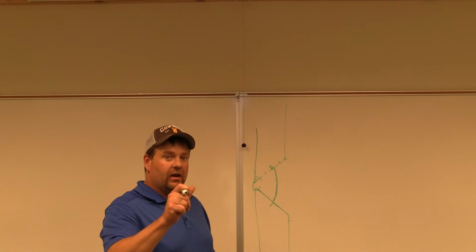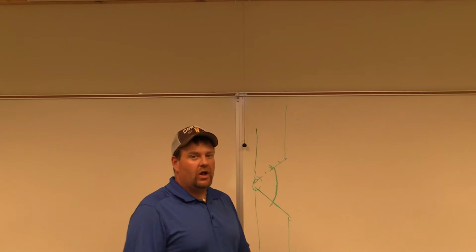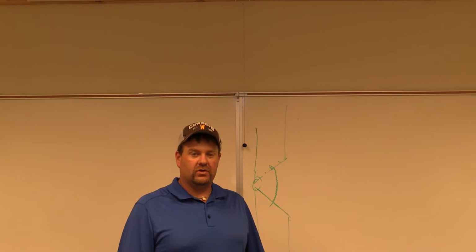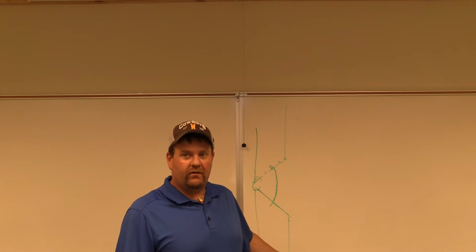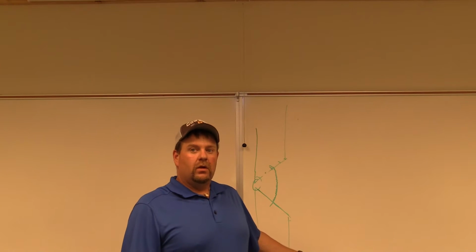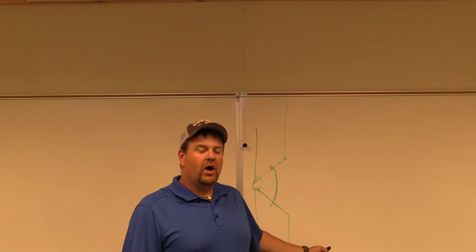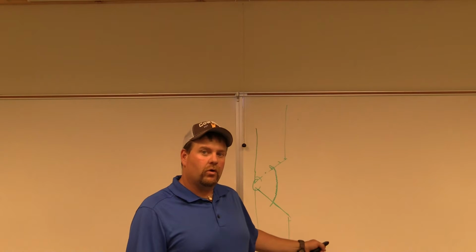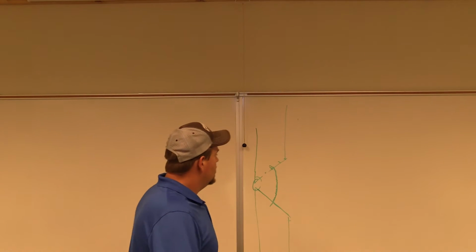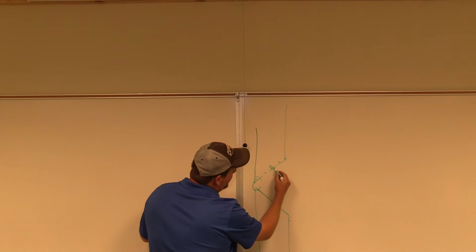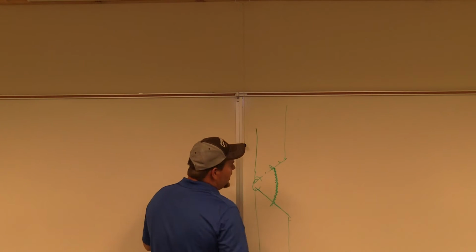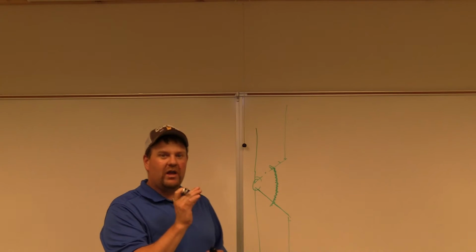So exactly with that, when we are doing multi-pass welding, especially if we're going to bend test it, and it's a critical weld or holding temperatures, so I do this even on a fillet weld. If it was on a building, a skyscraper, and I was welding it with wire, and it was going to stay in place, I would grind the top off. All groove welds especially I do. I want to come in here with the grinder, and I want to take just the top layer off to where it gets down to good, clean, shiny white metal.